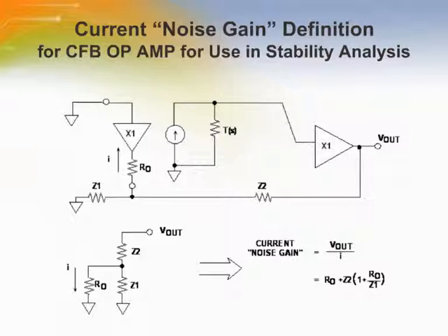It is for this reason that CFB op-amps are not suitable in configurations that require capacitance in the feedback loop, such as integrators or low-pass filters. They can be used in some filter configurations, such as Sallen-Key filters.